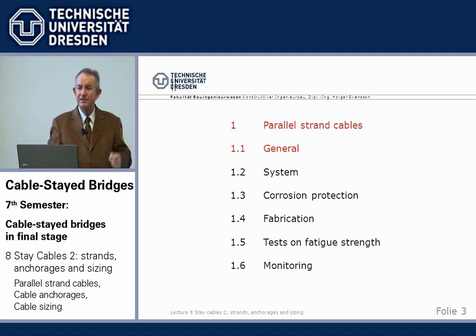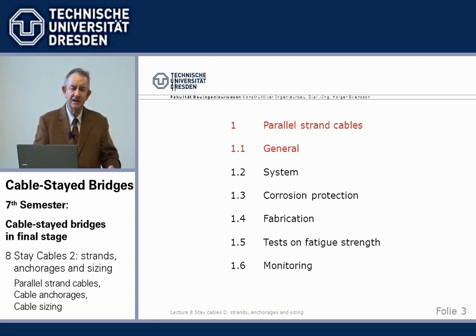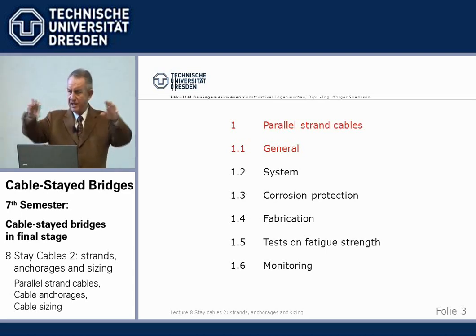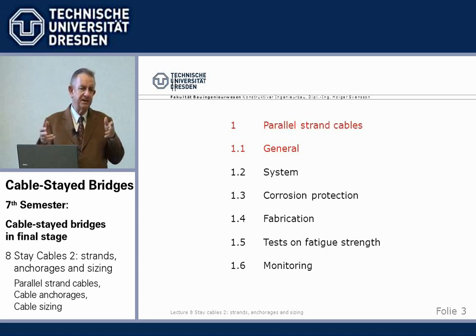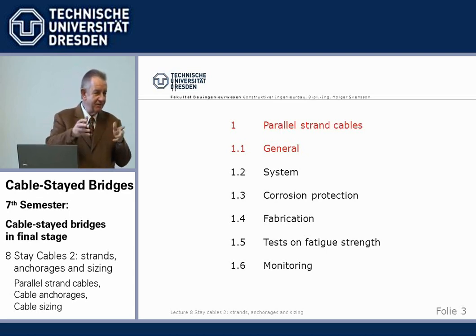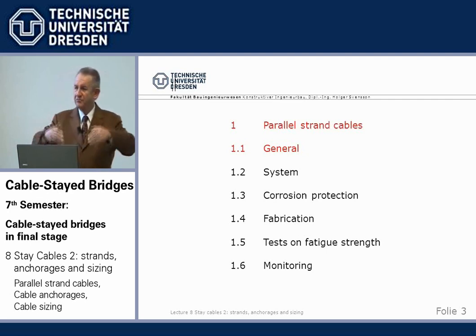Money talks. That was the basic idea, and the initial was also done in our office for the Olympic roof in Munich. And if you think of that, there are very thick edge cables and so on. We were the engineers for the Olympic roof at that time. And there were used parallel strand cables practically for the first time, but with a cast anchorage. Rather special, but it worked very well, so that was the beginning.